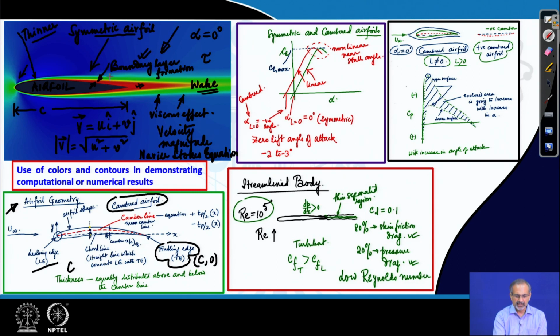Now, there are regions towards the later part, that means closer to the trailing edge part of the airfoil, where the viscous dominated region seems to have become much thicker, and therefore, just solving the boundary layer equations may not be good enough. Moreover, boundary layer equations may not give you the complete flow field information, it will just give you the information within the boundary layer.